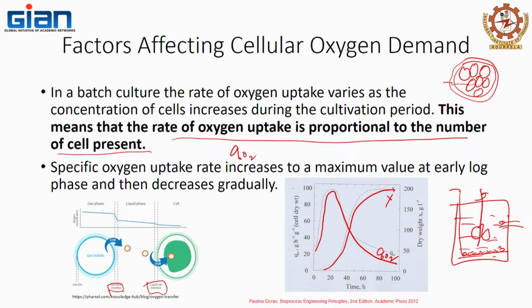The easiest example to that would be the taps that you see these days. The old taps were just the liquid coming out. These current-time taps give you that sound, shh, and it comes out in bubbles, like streamlines, right? It's less water, but it's very streamlined. So that's why it reduces the amount of water that you're using. Same way, if you basically break all the bubbles into very small bubbles, it will diffuse very easily in the medium. So agitation does impact the OTR, oxygen transfer rate. It's a very important parameter in that case.